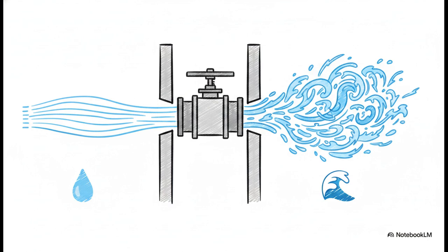So let's look at how it travels through the rock. At low speeds, gas moves to the well in a nice, smooth, predictable manner that's modeled beautifully by Darcy's law. But as reservoir engineers, we want high production. The catch is, once we open the choke on a high-capacity well, that gas accelerates so fast that it enters the chaotic, highly turbulent world of non-Darcy flow. And in that world, Darcy's simple math completely falls apart.